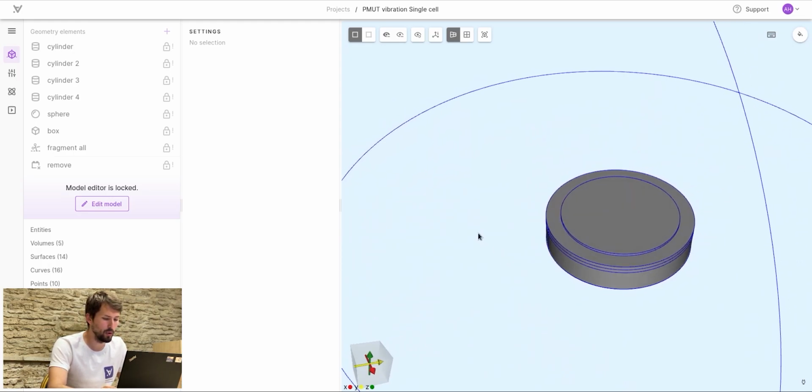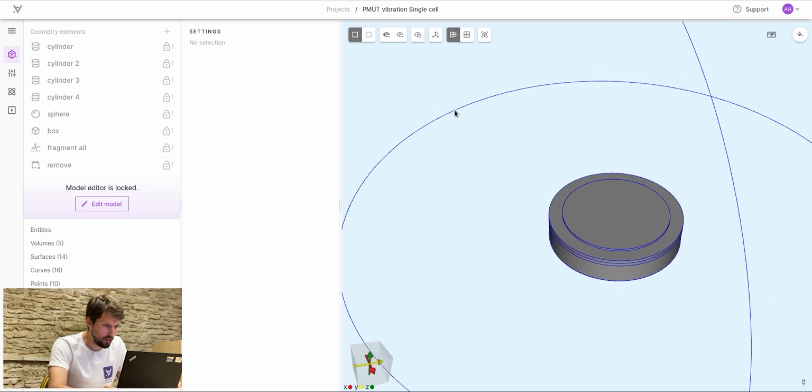And as the electrodes are driven with an AC voltage, you shrink and you expand the piezoelectric material, and this brings the cell to typically resonance frequency, and this emits or receives ultrasound, typically between 40 kilohertz to 10 megahertz of resonance frequencies, for, I think here it's a 100 micrometer diameter device, if I'm not mistaken.